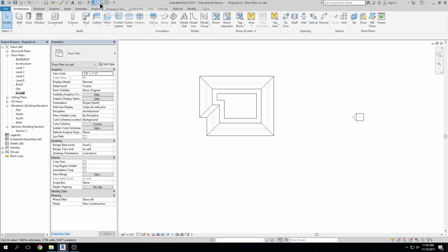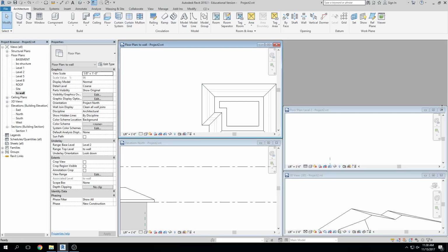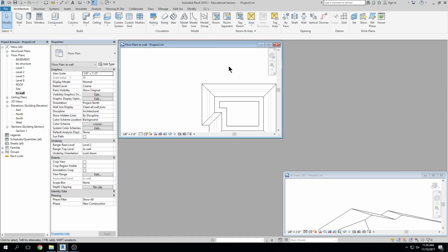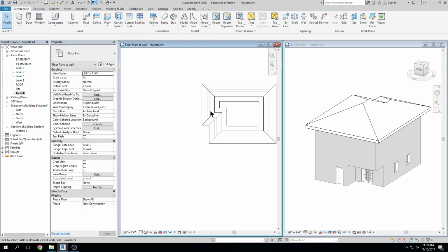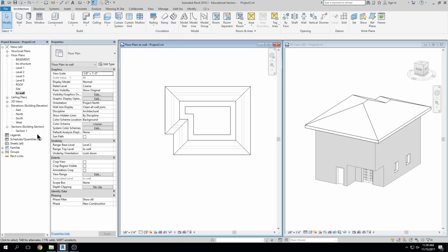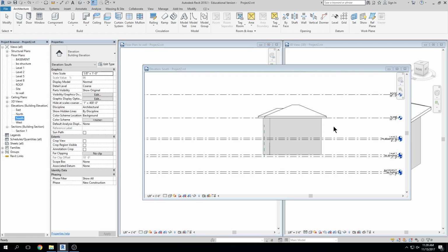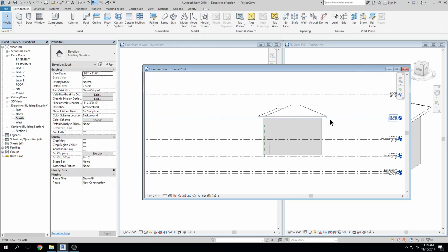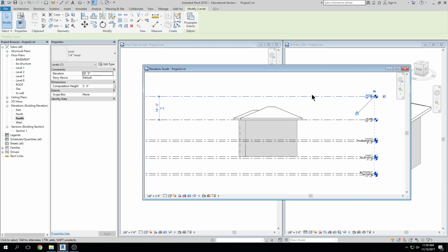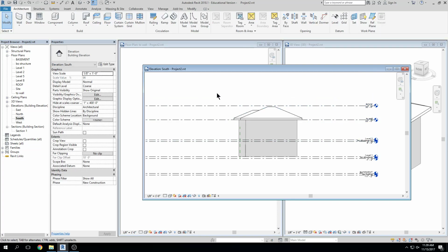And it's cut off because, let's close a couple of these. But it's there. Look, I look in 3D, it's there. It's cut off because of my view range. Okay, if I go to my elevations, right? I'm on top of wall, and on top of wall you only view up to a certain 3-4 foot range. And what I really want to do is view this from my roof. So I'm getting a cut, and there we go. And it's showing only part of the roof.